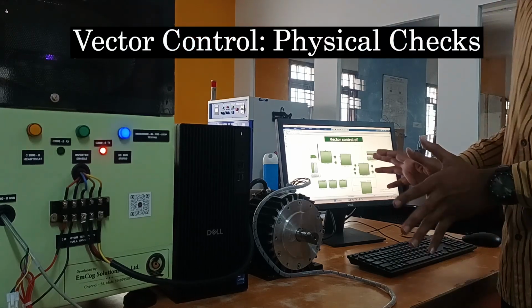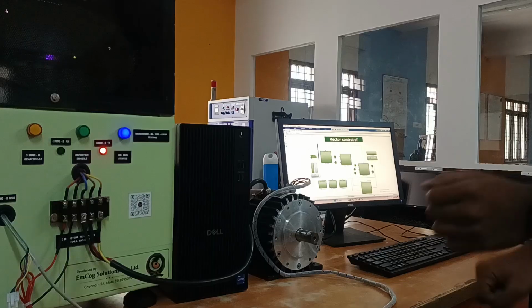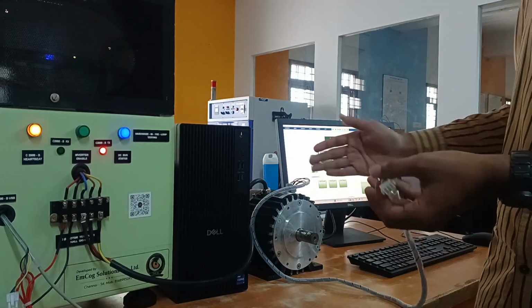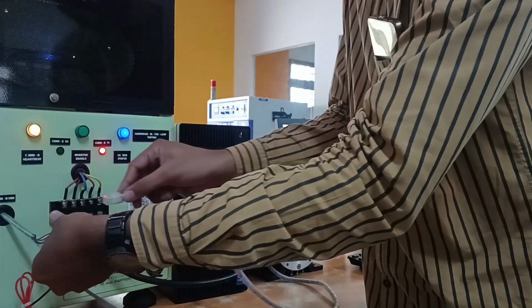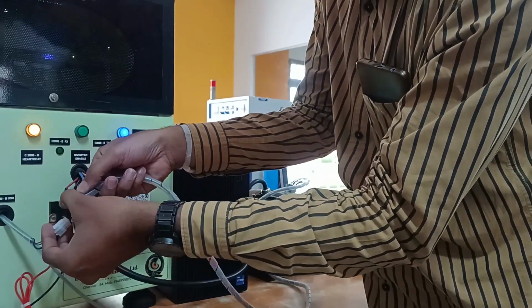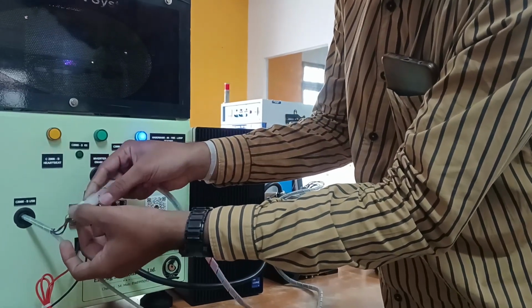Okay, let's see how to deploy the vector control algorithm and make this motor run. First, we have to connect the Hall sensor reading from the motor to the panel. Make sure you have a ridge that has to mate with this connector. You will hear a click sound.